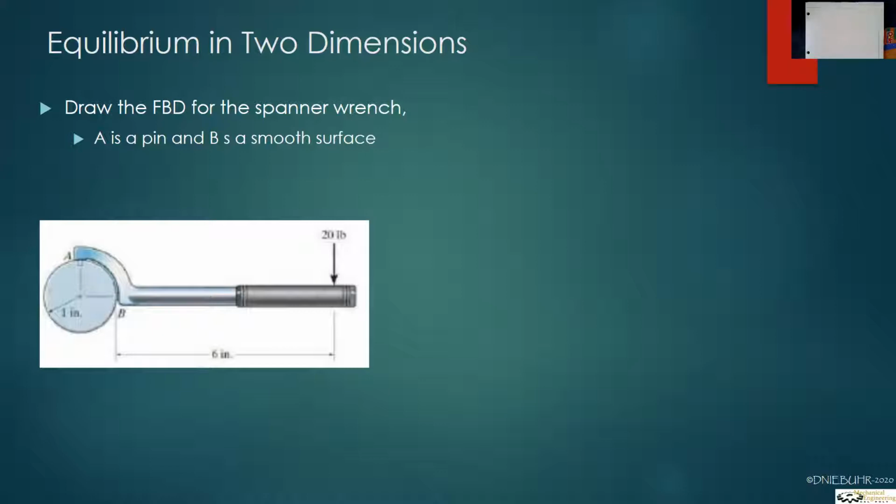So you have typically a hole in the shaft, and then at point A, there's a pin that will go into that hole, and then at B, that's just generally a point of contact that allows you then to subsequently turn. So B is a smooth surface. Now, hint, whenever you see smooth surface, that means there's no friction. And so we'll say that on and off, even though there really isn't friction in this chapter, but that's an indicator that you're only going to have a single reaction. So go ahead and write what you think is the free body diagram for this.